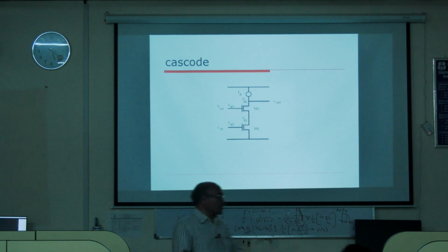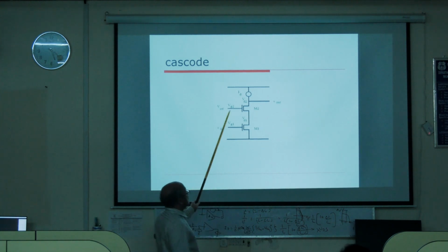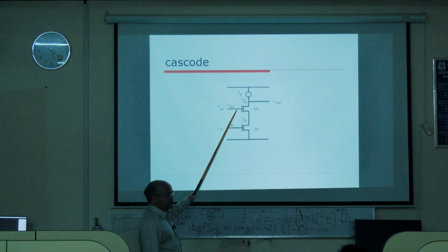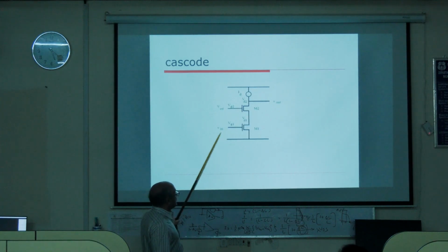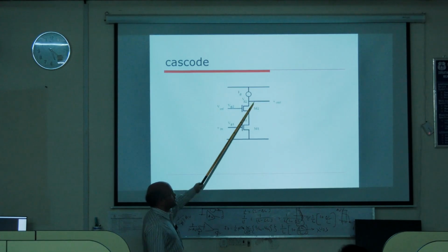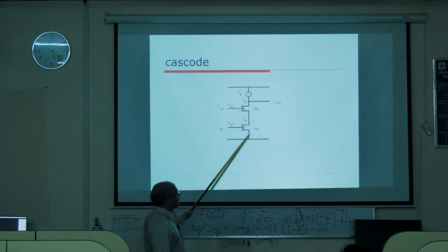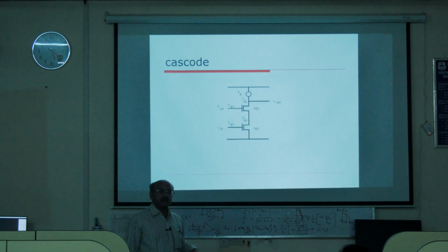Okay, so this is a DC voltage. Now what we would like to see here is, when you treat this as a single transistor, the input voltage is at the driving transistor and the output is taken here. So this is a single transistor. Now dID by dVG1 is going to give me the transconductance of that single transistor, gm effective.